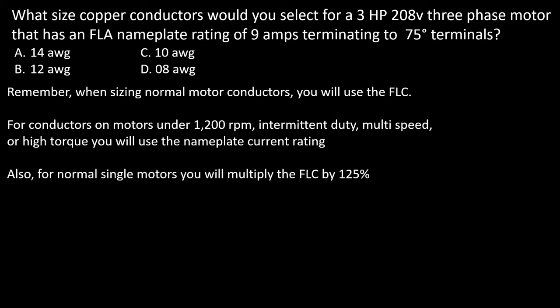Also, when we're doing normal single motors, we're going to multiply that FLC by 1.25. We're going to be doing some multiple motor questions next week, but this week we're going to be doing all single motors, meaning one motor, and we're going to be doing normal conductor sizing. So let's go ahead and jump in.